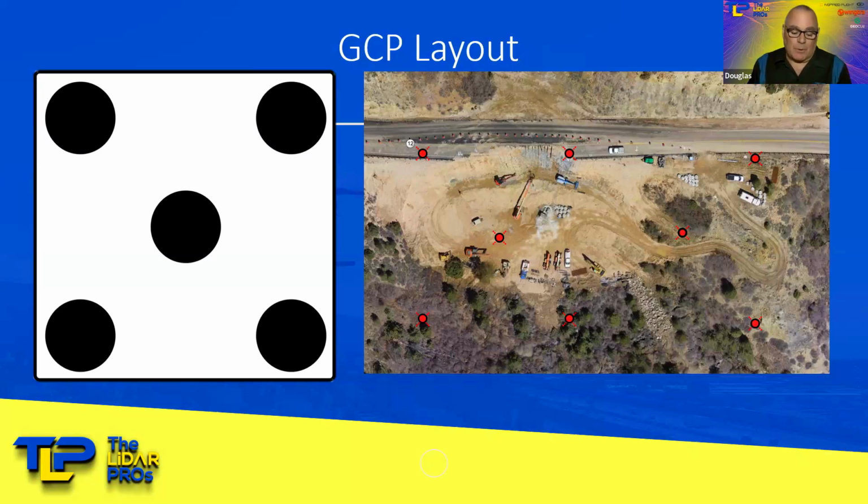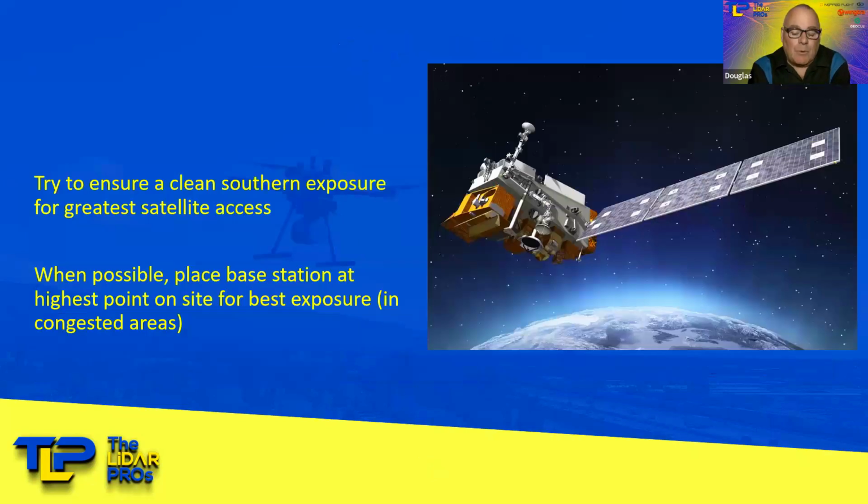But one of the other things that we want to consider, especially when we're doing this kind of work, is that where we can, we want to have our base station as exposed to the southern exposure, or the southern sky, as we can.